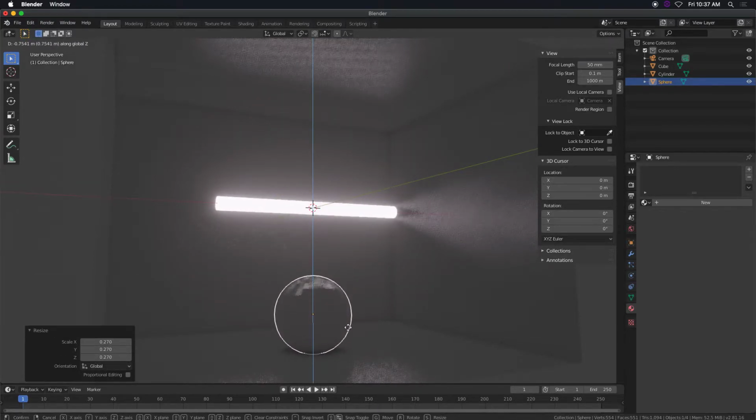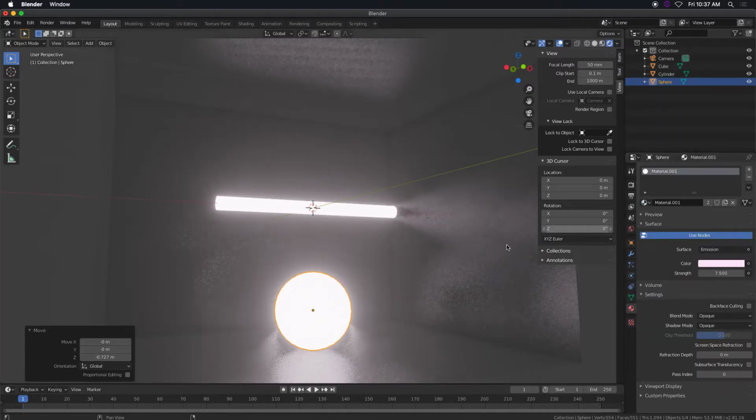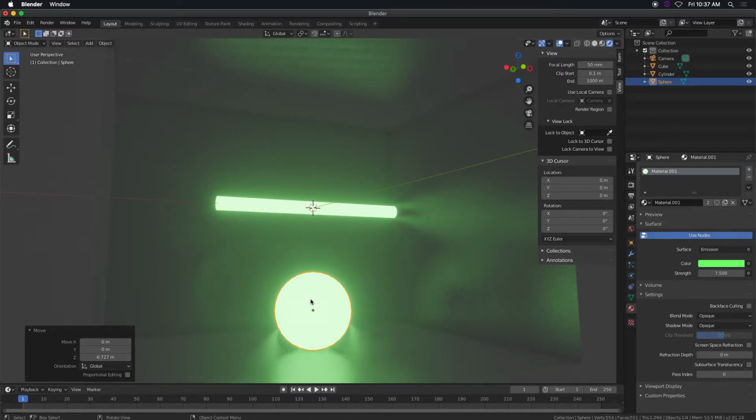So instead of applying the emission on this one from the ground up, you want the same emission. Instead of clicking New, there's this down arrow right here, which says Material 1, because I didn't name it, and then you just apply it. So instead of going New, Principled, Emission, and so on, you can just apply it there. Here's another thing we haven't done. When you manipulate this, guess what happens to the other one? It's the same. What if you want the same intensity but a different color for this?